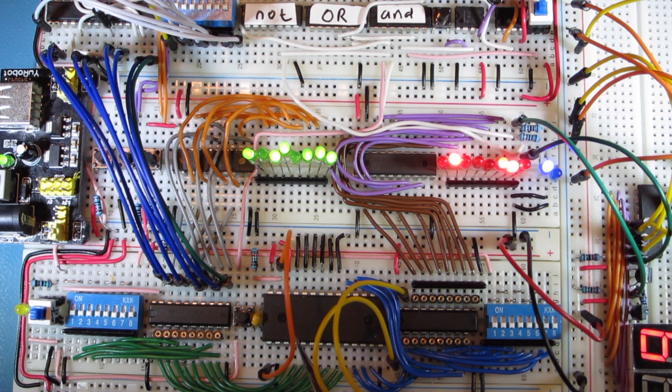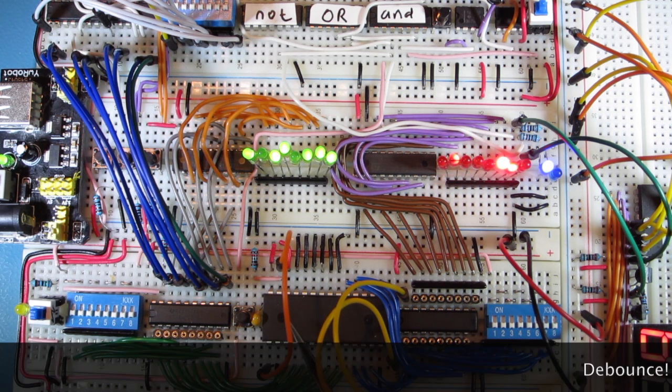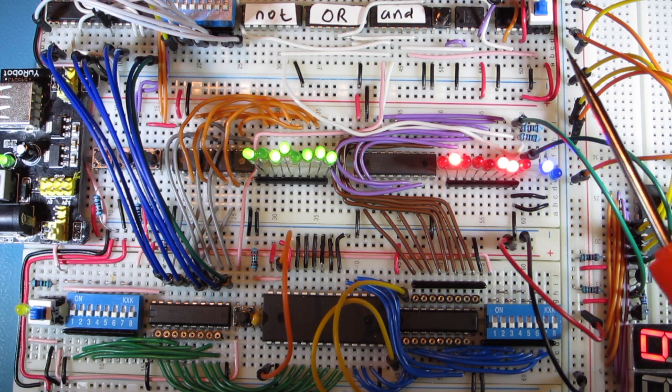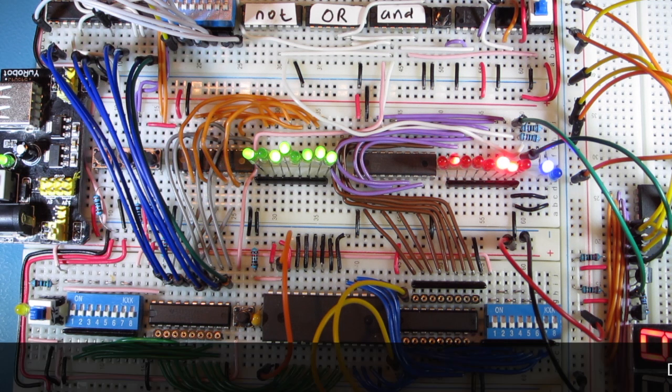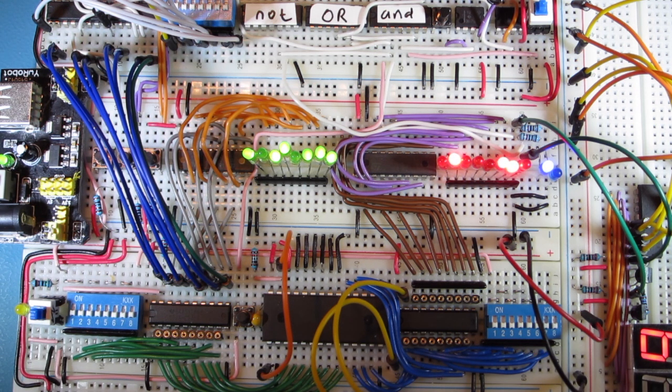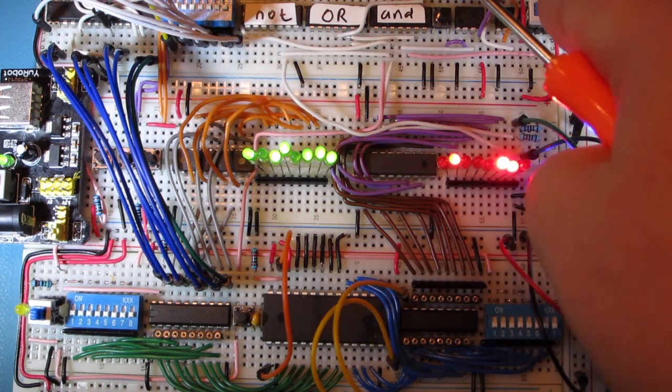On the memory, even if I do get a multiple pulse with this basic decoupling, it's not going to make any difference to the write signal. The memory will still write, but with the clock, if you get a double pulse when you press the button and it's not decoupled properly, that will cause two clock pulses, and you may find that your program or your circuit goes further than you expected it to on a single pulse.